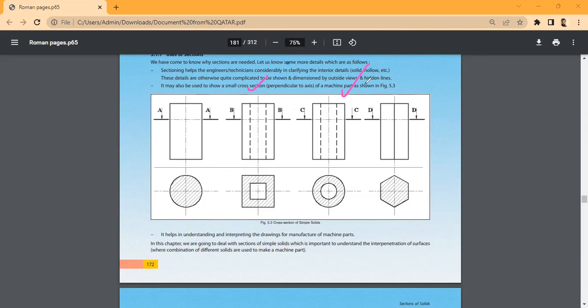It's a hollow cylinder. The cutting plane is parallel to HP and perpendicular to VP, and it's below the top side. So here, what about the section? Why are there no section lines in that central circle? It is a hole. Right. Then the fourth one.